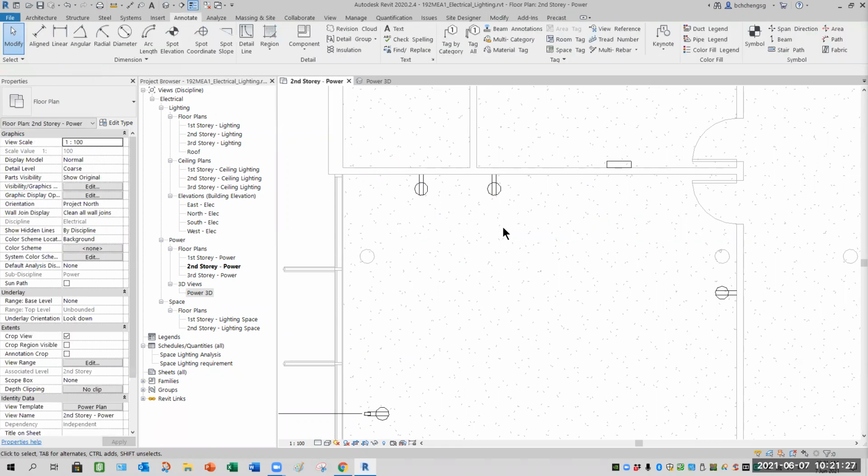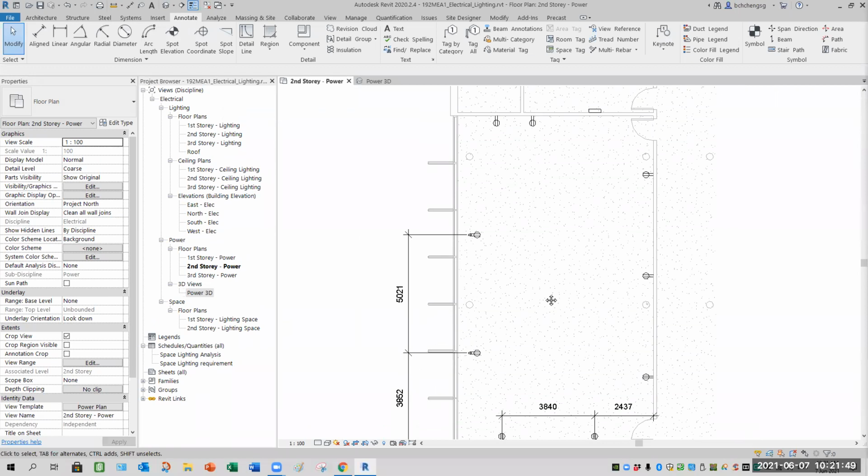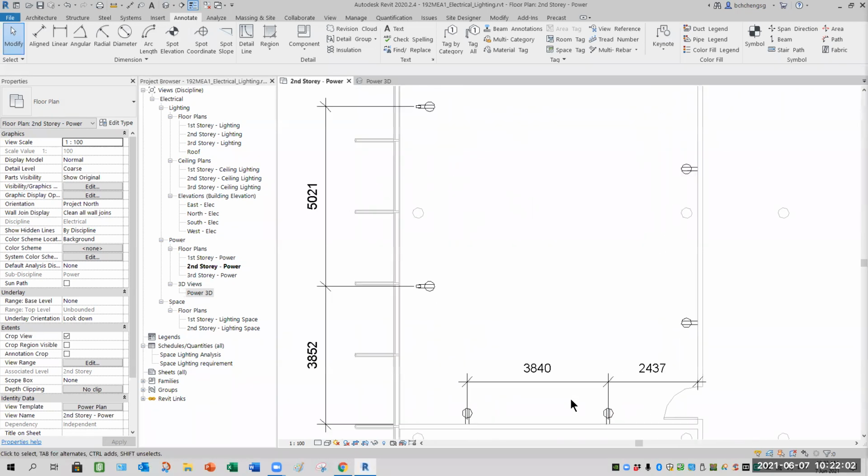Normally when you start to lay all this, you should already have the interior or furniture plan done up by the interior designer, so that from there you can plan where to install the power socket. So all this reference, you don't do ad hoc. If you can obtain the file from the architect or from the interior, then you are able to lay the power. All right, so this is important.